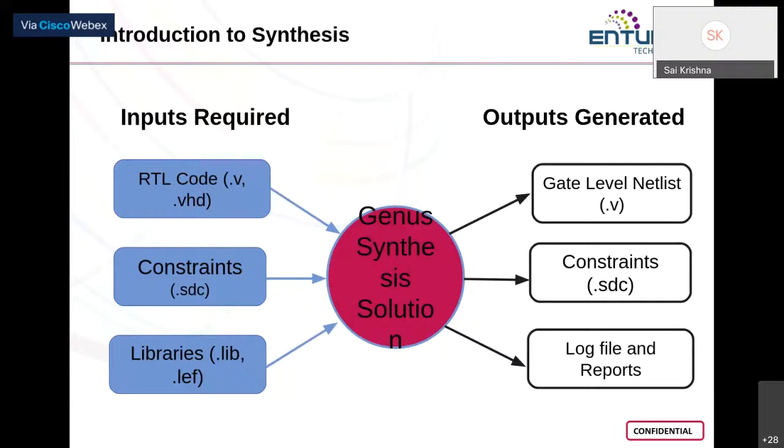Synthesis has nothing to do with verification. It is a part of your design process. RTL coding is design, functional simulation is verification. And now you again come back to design with synthesis. And the next stages, timing simulation and DFT, are your verification part again. So like this, alternately, we deal with it. That's why here you take only the main code, and then you also read your library files.